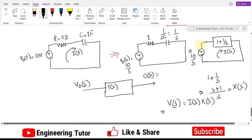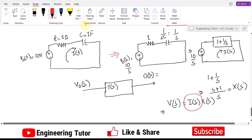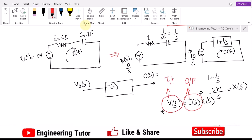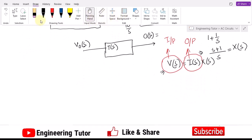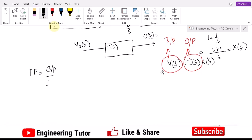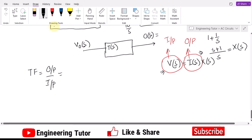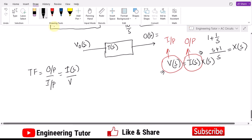So, all the values are known here, but this one here, let me change the color here. This one is the output, which is the required quantity, while this one is the input again. Okay. So, in order to find the transfer function here, what is basically the transfer function? So, transfer function is basically the output divided by input. Okay. So, the output here is I of S, while input is V of S. Okay. So, here it would be I of S divided by V of S.